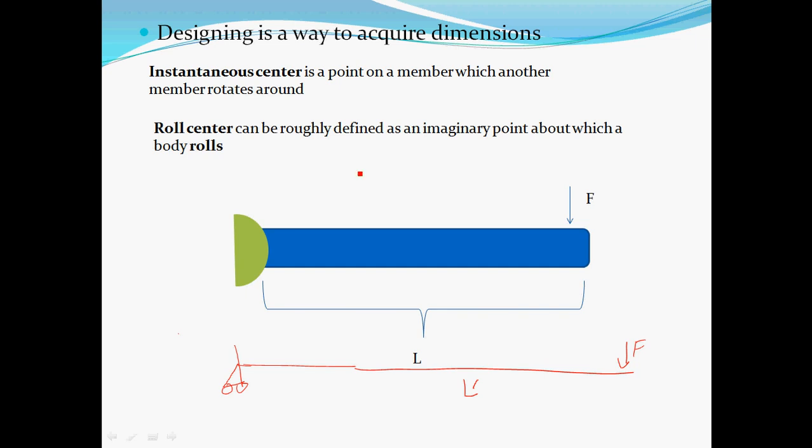See, my torque is equal to I alpha. Now my torque with the increase of length has increased. My inertia has also increased because of the increase in length, and inertia has a term of L square. So the increase in inertia will be more, so my angular deflection will decrease. Now this is very important. This means that if you increase the distance between the point of application of force and the point of rotation, then your angular deflection decreases. Why this is important, we'll discuss further.